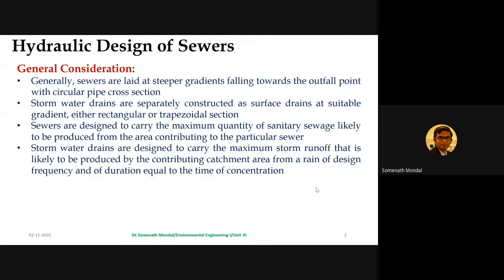Another thing is, these are not running full most of the time, so there is no chance of getting under pressure. It will simply move from one point to another while partially full, and that is the reason we consider them as open channel flow, and accordingly we apply different formulas associated with open channel flow to design the velocity and subsequently the discharge. So this is very important to remember.